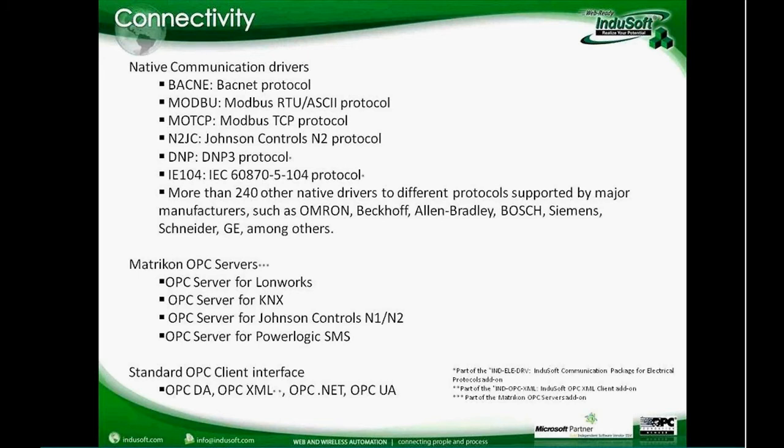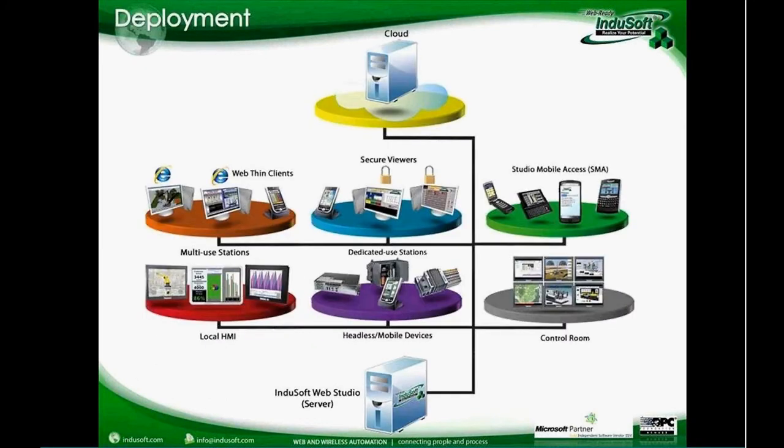In addition to that, in InduSoft we have a standard OPC client interface compliant with different standards, including OPC-DA, OPC-XML, OPC .NET, and OPC-UA. So again, it's an open architecture, and we provide several tools allowing you to bring data, consolidate data from different data sources, different equipment with different protocols, and then manipulate this data in a seamless way in InduSoft Web Studio.